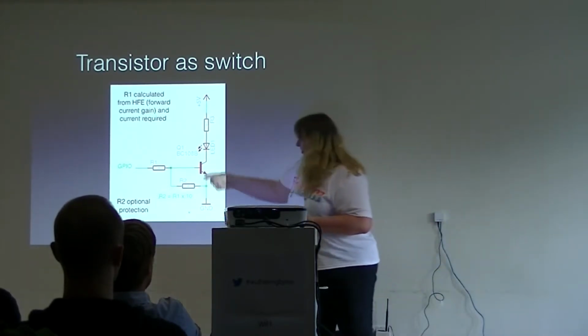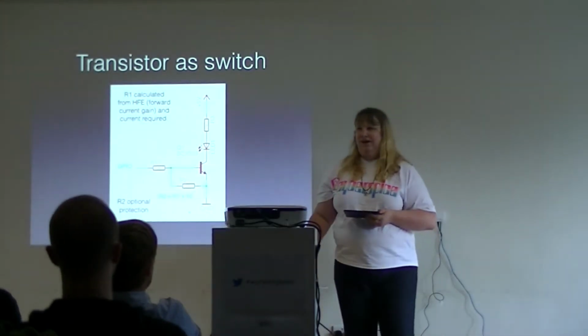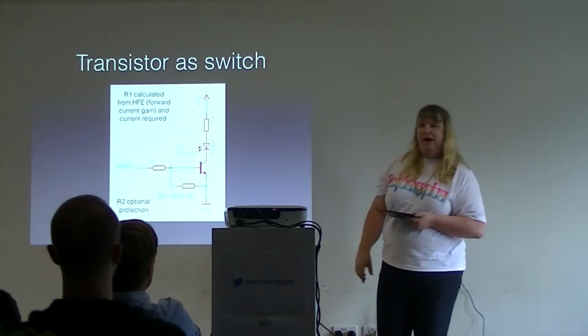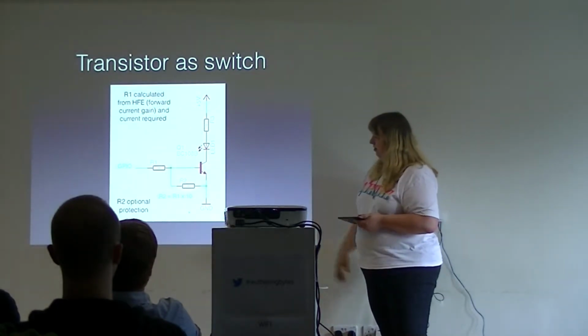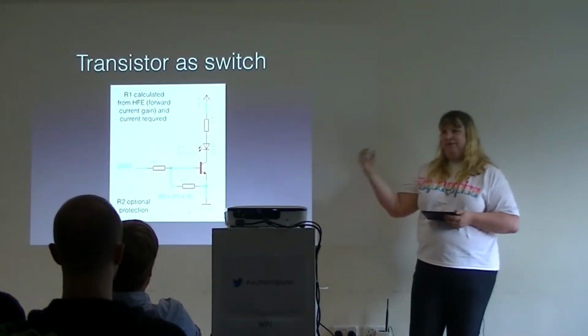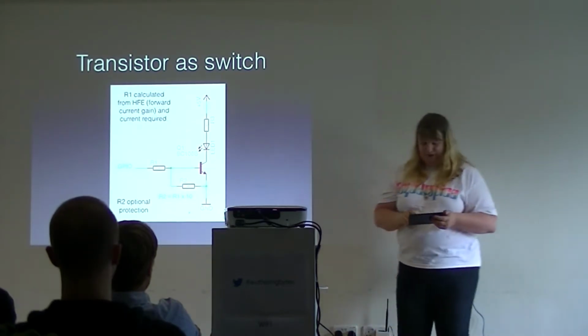So you'll get that transistor and that resistor together. But then you just hook up the LED and the other one as normal, and you can have a great big, enormous bright LED that uses half of 500 milliamps, and you're not going to blow your Pi up.